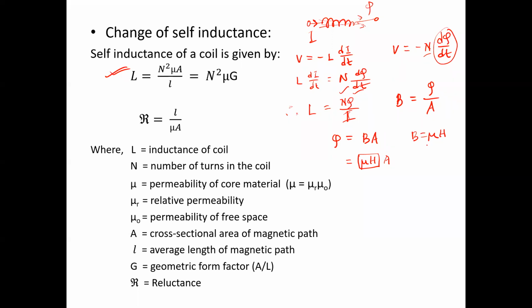The permeability of the magnetic path indicates the ability of the magnetic material to support the development of a magnetic field inside it, and H is the magnetic field strength or magnetic field intensity, which is proportional to the current, and the proportionality constant is often defined as the number of turns of the coil per unit length, and the unit is often represented as amperes per meter or ampere turns per meter.